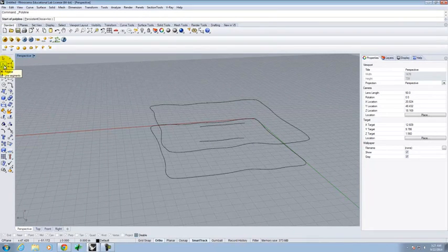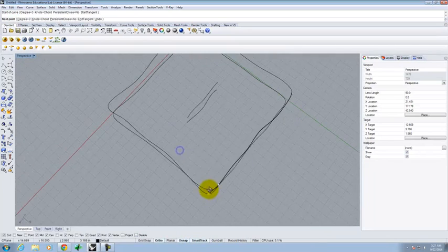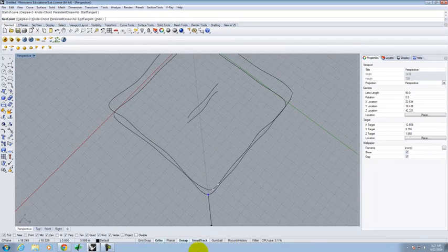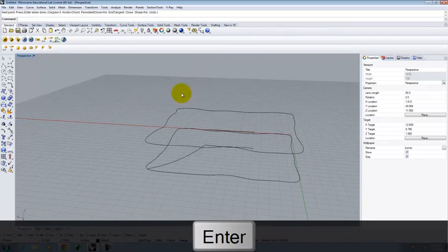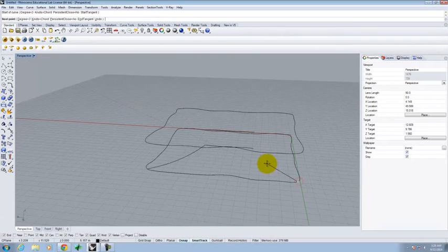depending on whether you use polyline or this control point curve, interpolate points, which is the second one under the complex curves, is the one that I tend to use a lot. So I'll just point that out. And what I'll do is I'm going to turn back on my object snap, and I'm going to snap a line, and I can turn off ortho here on the bottom, that's going to connect to this center point right there. And I'll do the same thing from this corner.